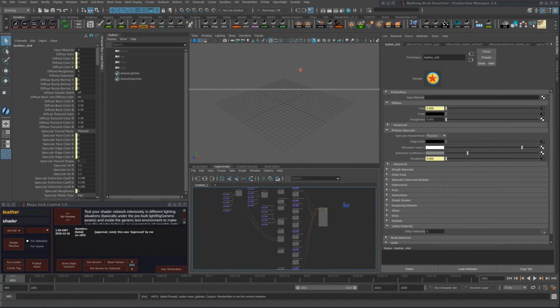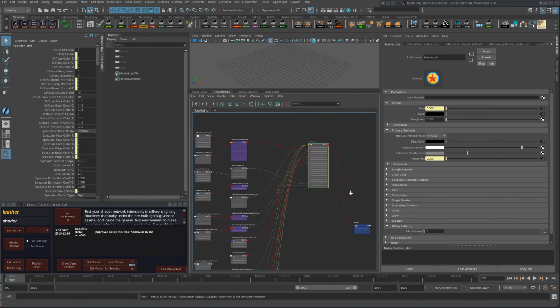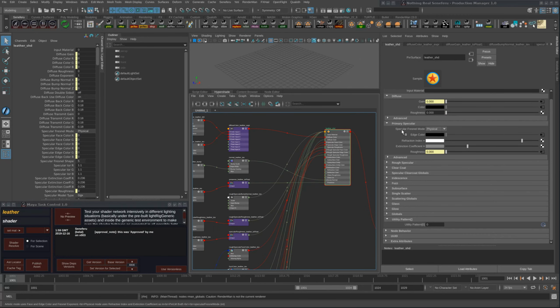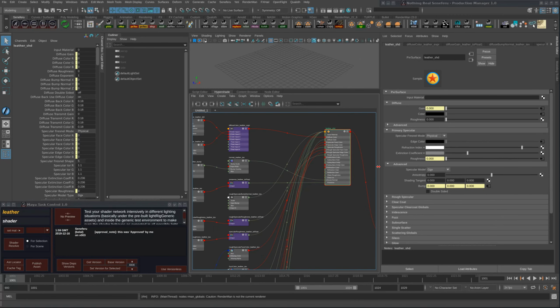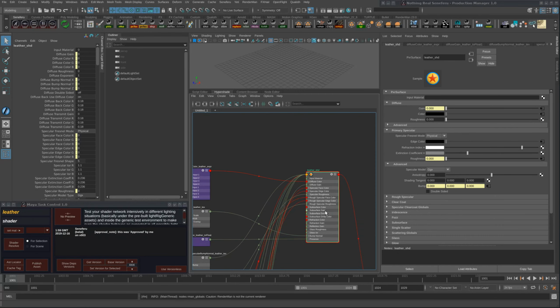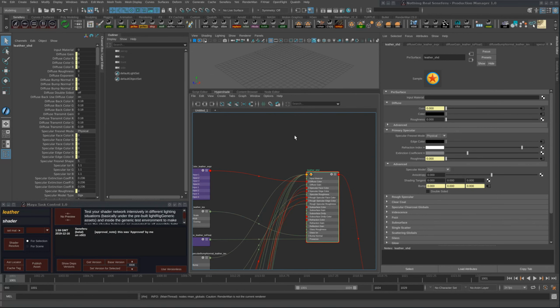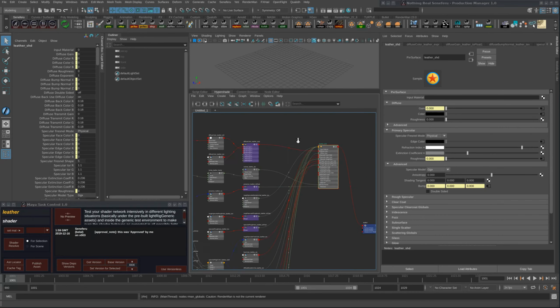If you notice here, you will find that the shader has some texture maps connected to some of the shading components, not all of them. What we do is that you can tweak the shader parameters as you want, then you can attach textures to the shading components you are expecting that this type of material will have, like diffuse, specular, subsurface scattering, or whatever the shading components you are expecting that such a shader should always have.